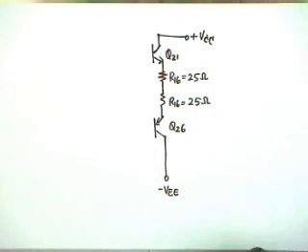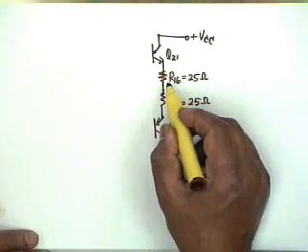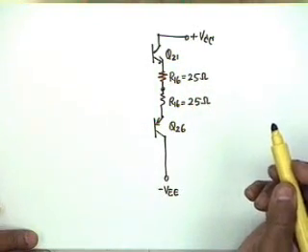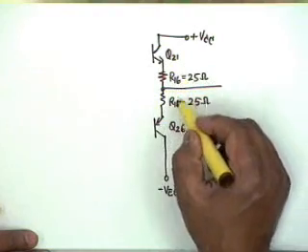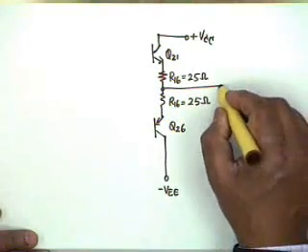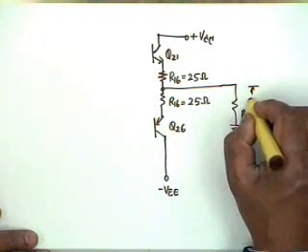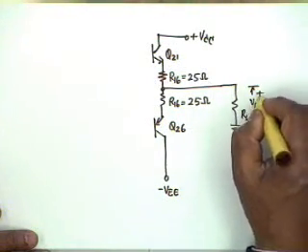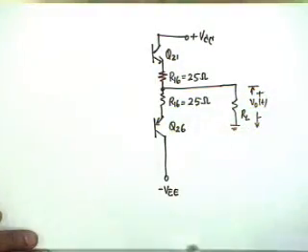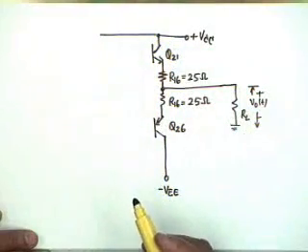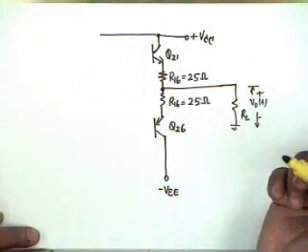The load is connected from here, from the middle point. Obviously it has to, from the symmetry. I will explain the purpose of the R16 a little later, and then you have the RL here, and of course the voltage output is across the RL, V0T. Now from the collector you require the drive. To avoid crossover distortion, you require two diodes which have exactly 0.7 drops.